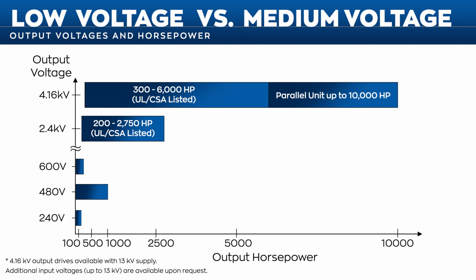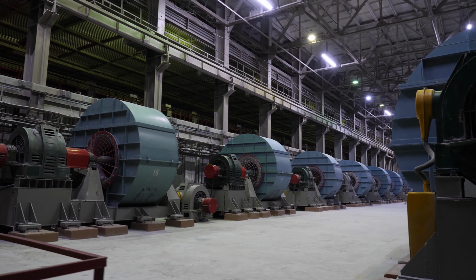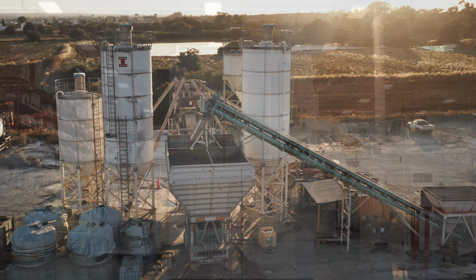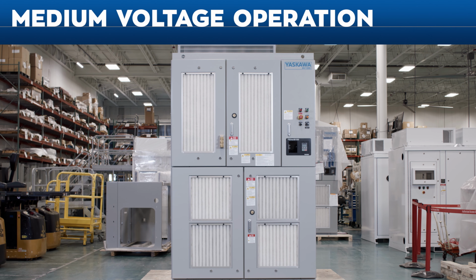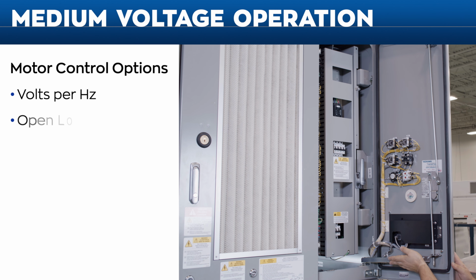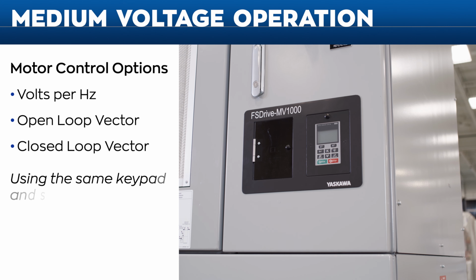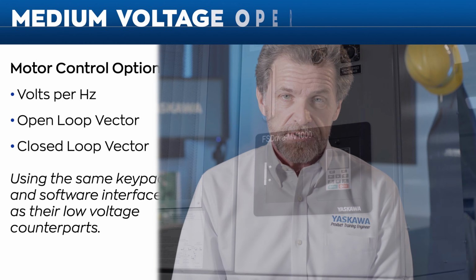MV drives are used on similar applications as LV drives, but on a much larger scale. Common applications include compressors, pumps, mixers, and conveyors. Medium voltage drives function much like low voltage drives. They may be programmed to provide volts per hertz, open loop vector, or closed loop vector motor controls using the same keypad and software interface as their low voltage counterparts.